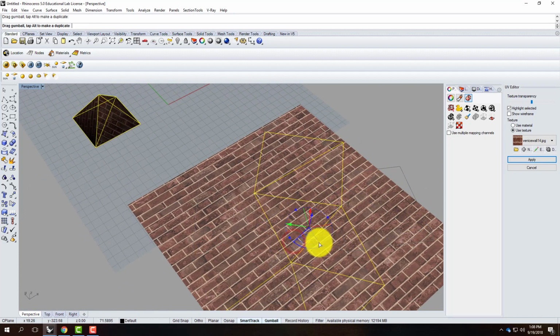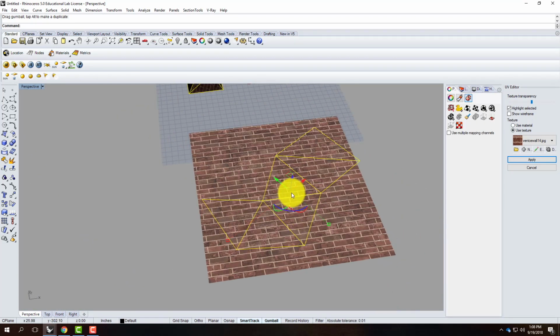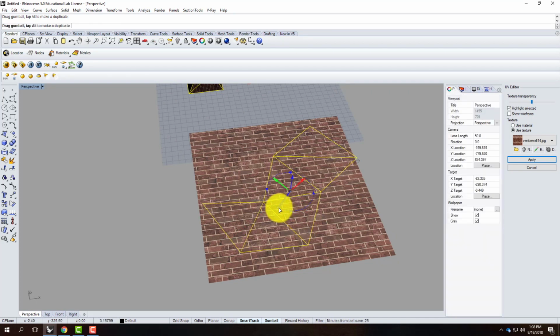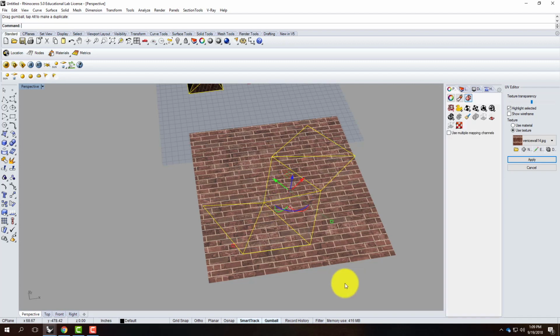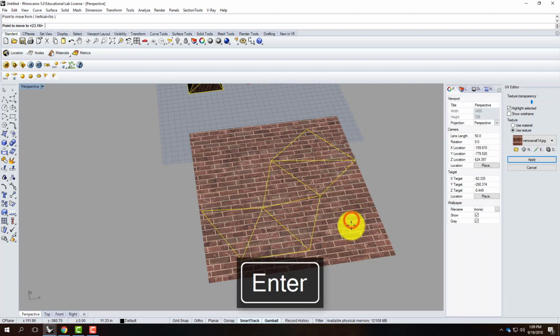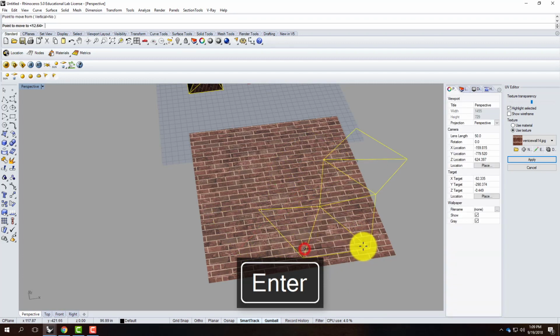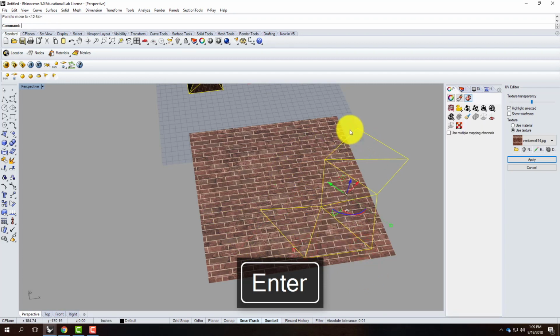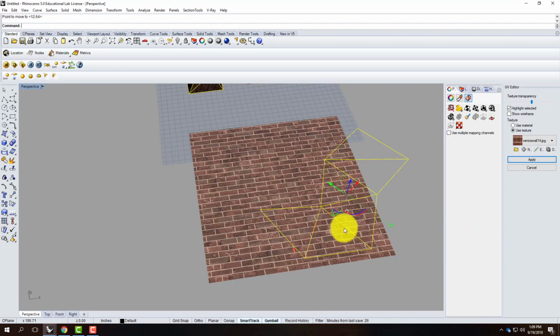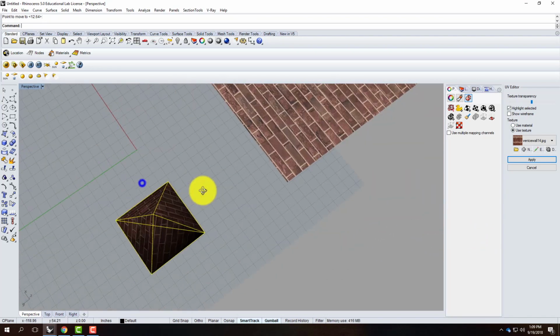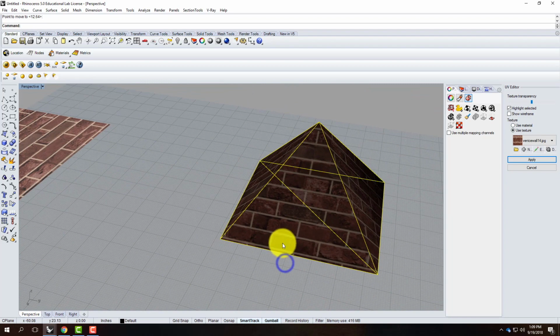So I could rotate my object to have one face apply in a certain direction. I could also move to control how and where on the texture. You can, by the way, move this so that it's off. It's as if this texture keeps repeating. So once you have it set, you can come over here and say, oh, there's that side. It's applied perfectly. I'm really happy with it. That's the side I'm going to render. And ultimately, you can render it.